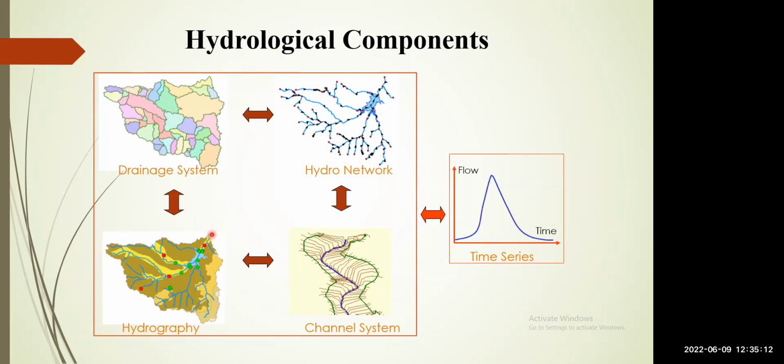So how can we say that this point has the watershed catchment area, including this whole area? Because if some rain is flowing here, that water flow will be connected to this stream, and then this stream will be connected to the main stream, then going toward the river, and then it will go toward the ocean. That is the overall area calculation.